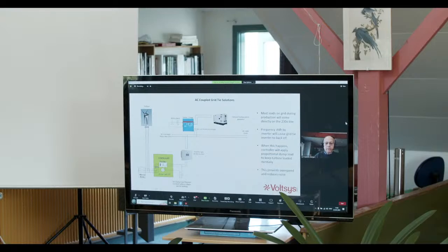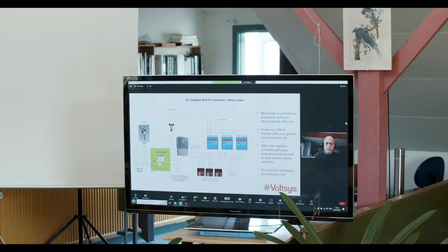And right up to the point where it reaches 53 Hertz, and then it switches off the inverter and all the power from the turbine goes into the dump load. And that, of course, can also work over a three-phase system with 3 inverter chargers, working into the AC hot out of the 3 inverter chargers.